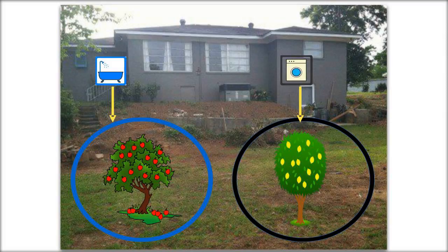And looking at this picture, this is a common situation, that you have different sources of gray water and then you have different parts of your landscape. So if you take the source and water the area closest to it, that can help you irrigate a bigger landscape overall. So in this house, the shower is on the left side of the house. That water could irrigate the plants towards the left of the house. The washer's on the right. That source of gray water could irrigate to the right of the house. So look at your different sources and think about where is the most logical and easy place to send that water.